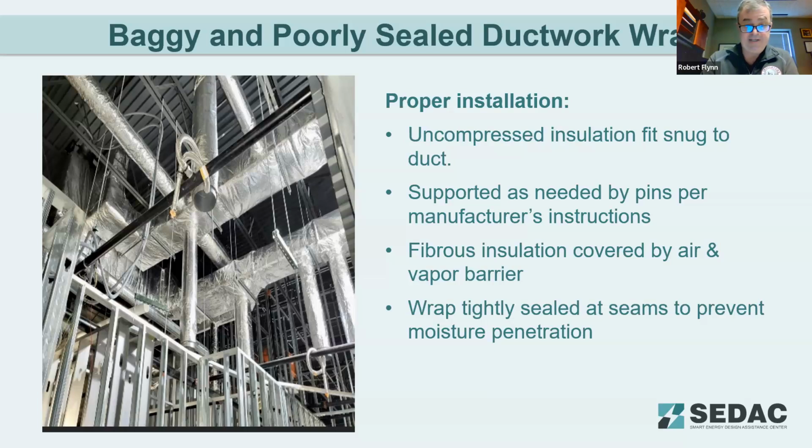I've seen it where it hasn't been done, and then actually I've just recently on a job saw that they sprayed spray insulation around the ductwork without even sealing the ductwork. There's just a variety of problems that go with that. There's a potential 25-400 flame spread issue if it doesn't have a sealer on it. As it breaks down chemically, it gives off a chemical reaction, and if you don't have the duct seal, it's actually going inside the duct.